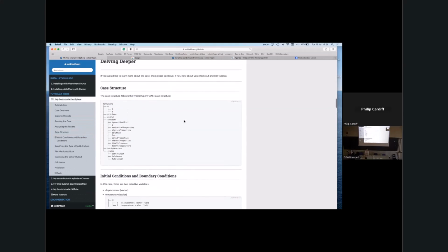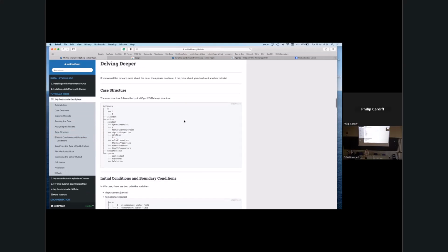So that works, but for the FSI part, there is a branch, maybe a stale pull request, where somebody did port it to use thermal coupling to couple the interface, but I'm not sure of the status of that. It wasn't integrated because there were a lot of changes. So you could definitely do it with preCICE. You could use this solids4foam solver, pick the thermoelastic solid model, thermoelastic mechanical law, and then couple it with preCICE. I think that should work. It would actually be nice, it's a good idea to add a tutorial on that. Maybe that's something we should do.